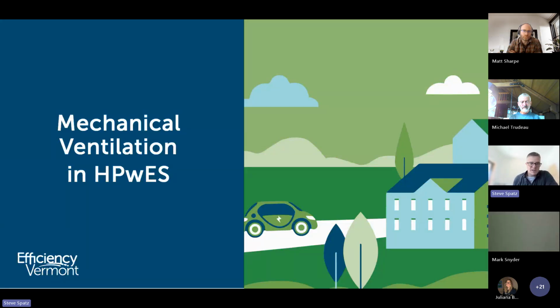It's also just the industry standard for ventilation design for residential buildings, as is the ASHRAE 62.1 for commercial buildings. So we're going to get into the details of the standard and then also talk about the application of this in homes, like what are your options to comply with the ventilation rates that are going to come from the ASHRAE 62.2 calculations and the standard that's required for the types of homes you're working in.